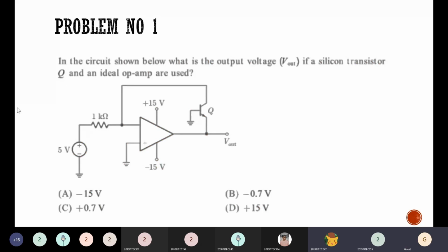If we are able to compare the given circuit with some standard applications, then with the help of those expressions we can directly find the output. And if it is not a standard application, if it is some new circuit, then we need to apply KVL or KCL, write some loop equations or nodal equations, and calculate the required parameter.